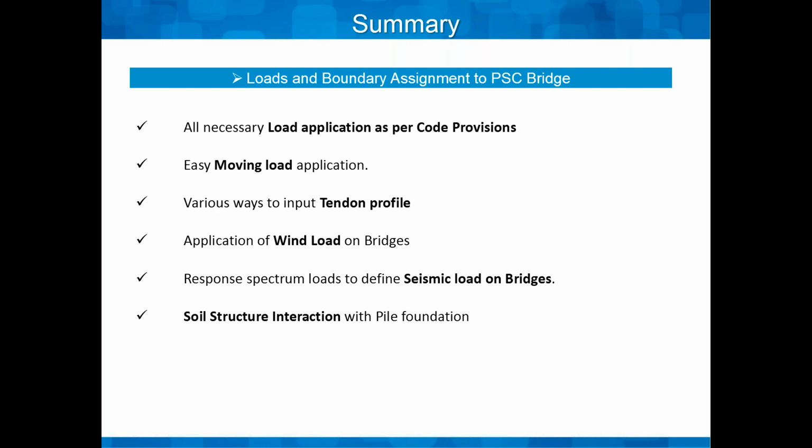There were gravity loads also, which we applied with the help of element beam loads. Then the response spectrum loads were available in MIDAS Civil for applying the linear dynamic seismic load on bridges. We also discussed soil structure interaction that can be done for pile foundations. So that is it from my side.